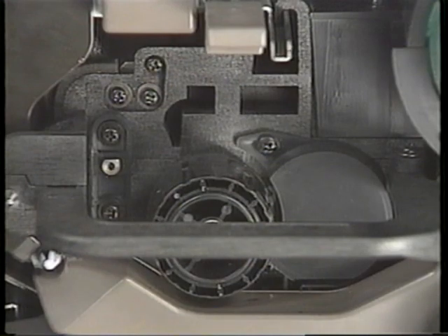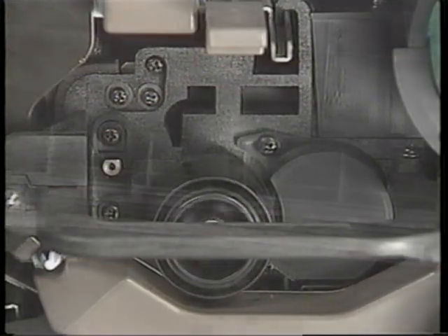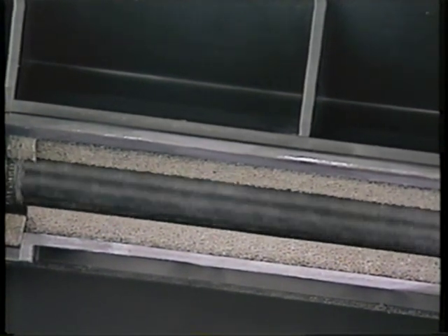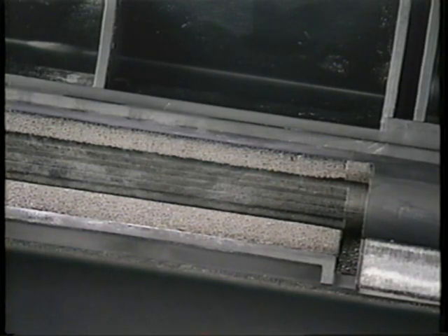To correct this undertoned condition, the copier's control system triggers a toner supply mechanism. It's often a special roller inside the development unit that scoops up a small amount of toner with grooves or ridges, and then drops it into the development unit. As soon as image density is dark enough, this mechanism is shut off to prevent too much toner from entering the system.